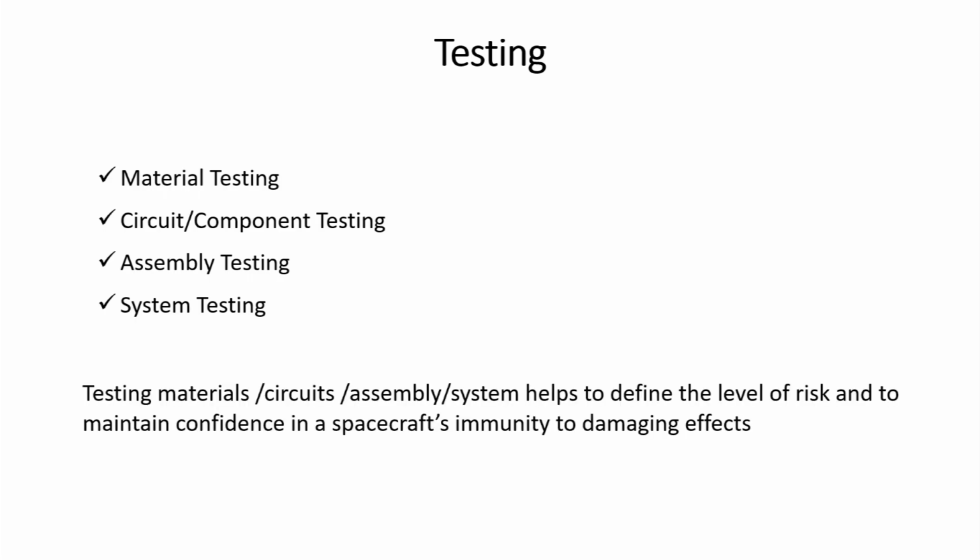Once you do all those tests by simulating the space environment, it helps to define the level of risk. Then you will know the reliability, on which we will do a chapter or a module. You have to assess the reliability. What is the failure rate? Suppose I have tested some 1000 components, what is the failure rate, and then we can assess the reliability over time.